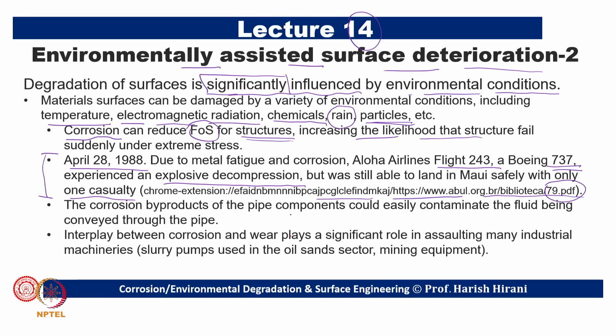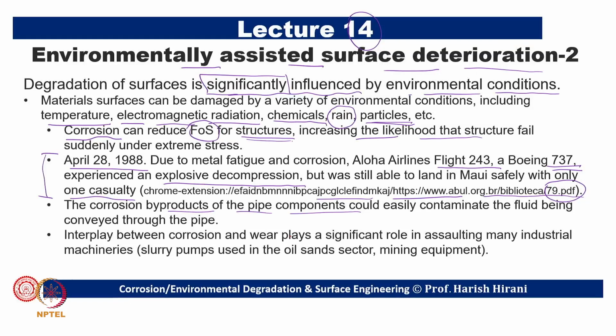So, even though we say the fatigue limit was initially x hours, because of the corrosion it has reduced to 0.6x or 0.7x or something like that. Another thing we have realized many times is with pipe components. Drinking water comes from pipes, and many times these pipes are made of steel or iron or some compound of that. In this case, we often find debris or contamination in the water because of corrosion byproducts, which are harmful to health, and naturally those pipes need to be changed immediately. That has been observed a number of times.